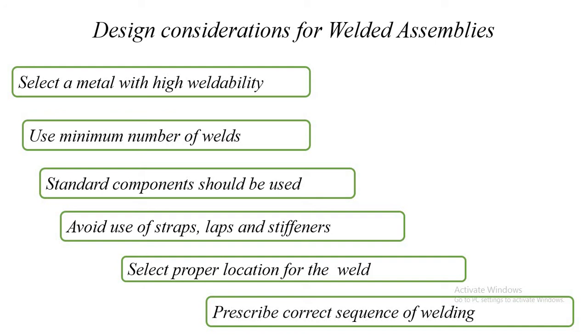The designer can increase the stiffness of plates to be welded by providing or increasing the bends, ribs and corrugation using pressing operations. Stiffeners are needed to provide rigidity, but it is preferred not to use external stiffeners as it increases cost.